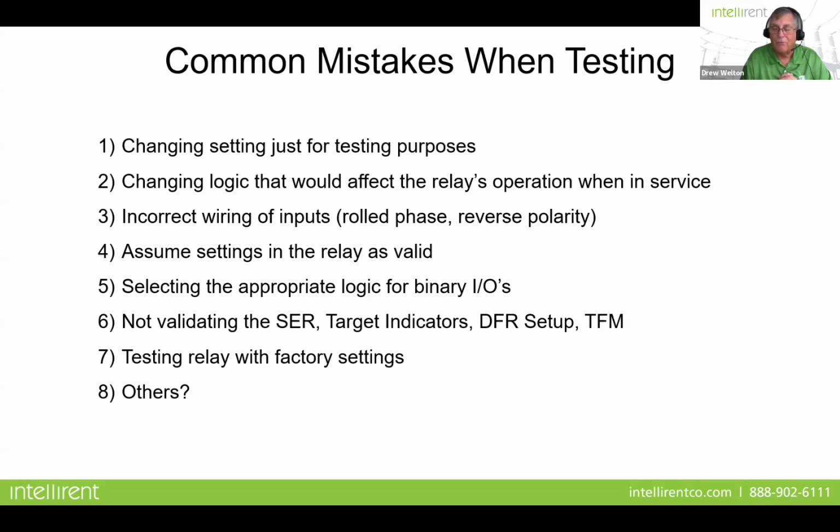Always verify the setting by looking at the nameplate of the transformer to make sure that those values were input properly. Assuming the settings select the appropriate logic for binary inputs and outputs, not validating the sequence of events record, target indicators, DFR, or testing the relay with factory settings is kind of a no-brainer, but I've seen it happen.